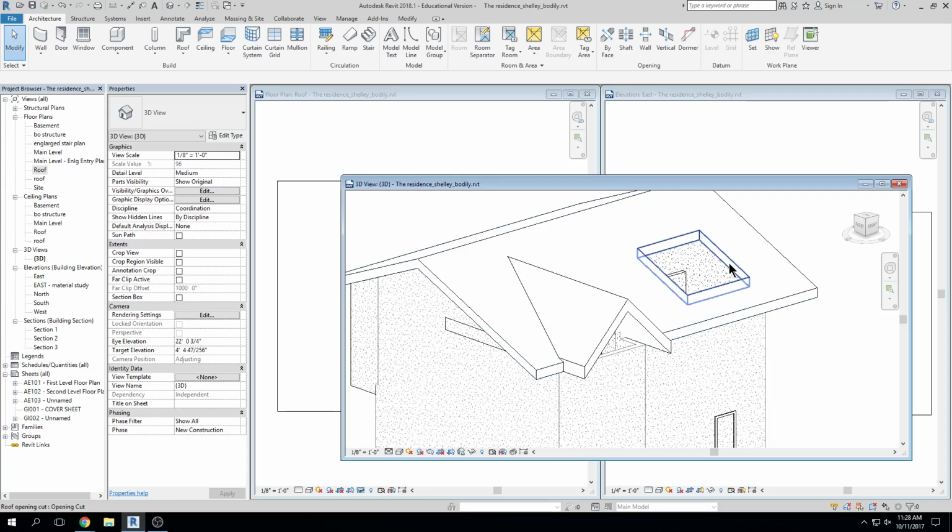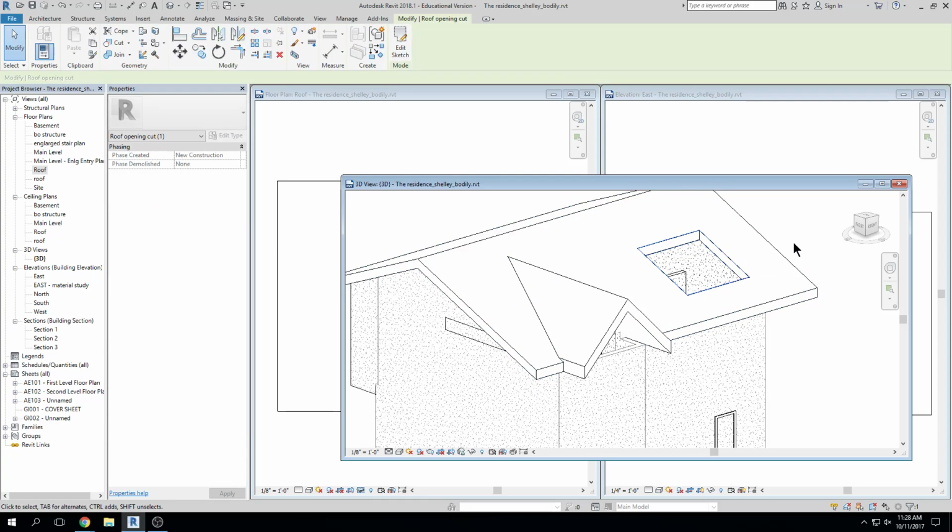But it's not. Now, it is similar to a shaft opening in that the opening is considered an object and the opening is a void, right? So any of you that have used AutoCAD in 3D, when you model in 3D in AutoCAD, and in Revit actually, you can create solid geometry and you can create void geometry, right? And so by doing what I just did, I didn't actually cut away the roof so that it's gone forever, you know, I created a voided opening in that roof, okay?